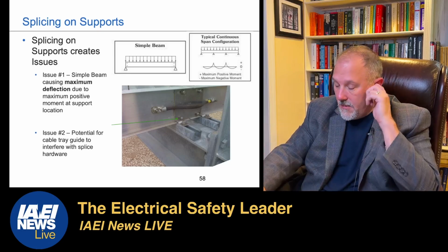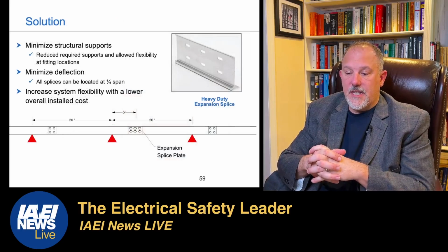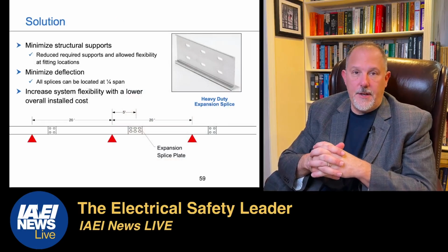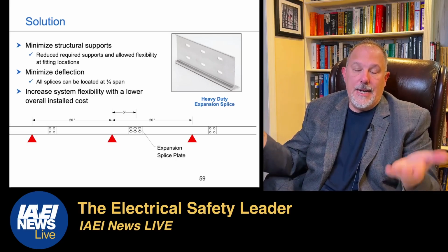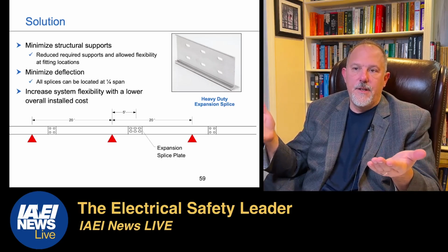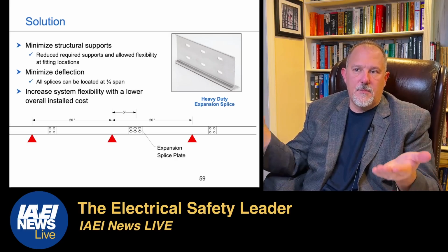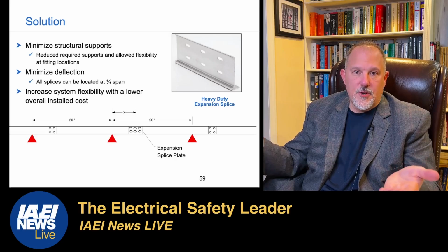Now, some manufacturers may give you expansion splices that are heavy duty, or they may have other types of solutions. I don't know. Talk to the manufacturer. Tell them you want to reduce the number of structural support members that you have to support the cable tray.